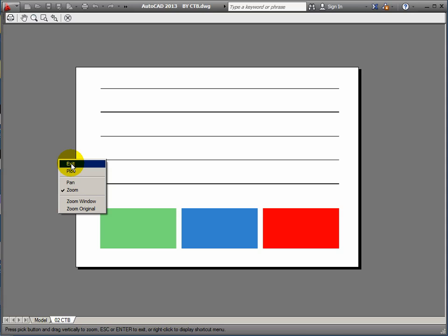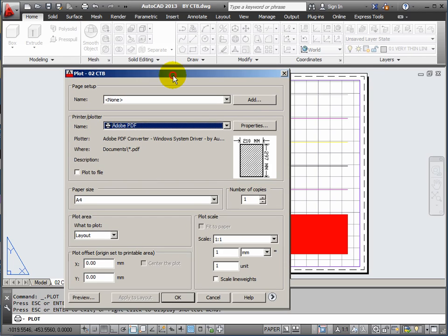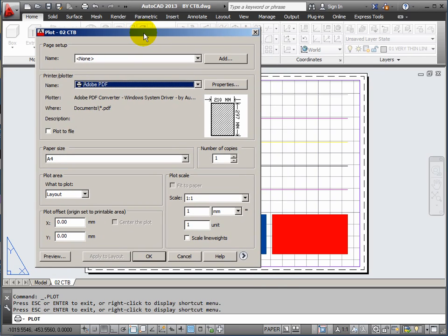Now, my black and color CTB has a very limited set of colors set up. I've seen CTBs set up where basically maybe every 10th color on the chart is used, and this gives you lots of colors to use for different objects in your drawings, and it's not over the top in the number of colors, so it can be quite manageable.